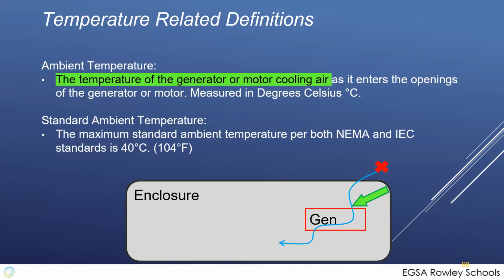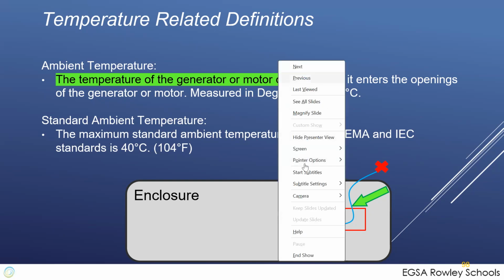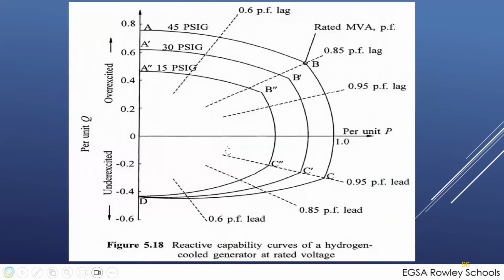Some quick discussions on temperature. Okay, you need to stay within that curve. And what I didn't show here, I don't know if I can draw it or not, but your power triangle that you know and love is kW on the horizontal axis, kVAR on the vertical axis, and kVA becomes a diagonal. For some reason I can't draw. Every time I go to annotate on here, I go to the next slide, but there's a triangle that the power triangle becomes in this part of the curve.